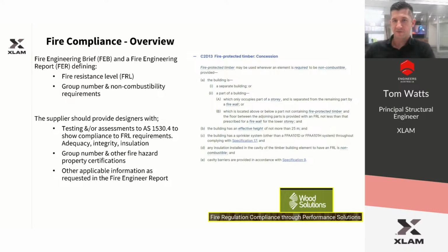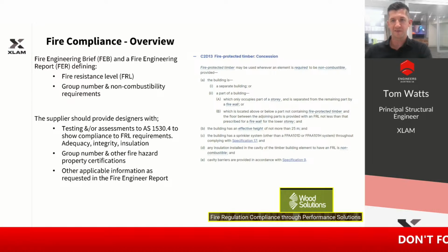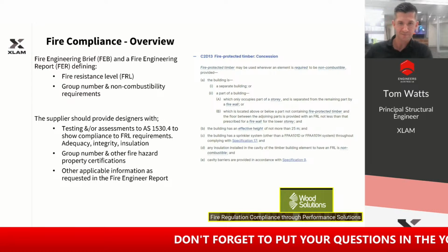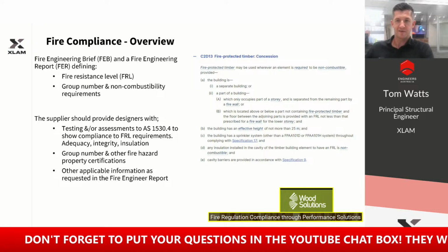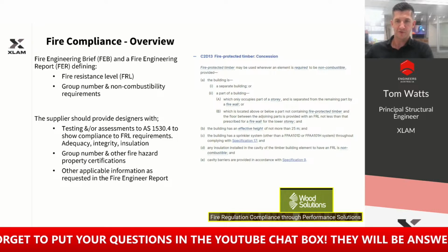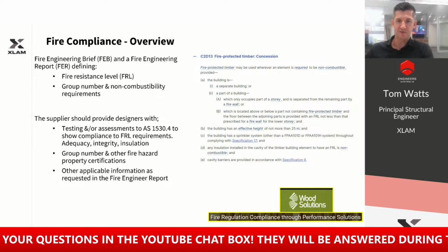In terms of the process that structural designers may need to be involved in, generally a two-stage reporting process is adopted, comprising initially the fire engineering brief, followed by the fire engineering report. This process involves the relevant stakeholders who, in addition to the design team, client and building certifier, may include the fire brigade, local council, insurers or other parties. The purpose of the fire engineering brief is to communicate to the stakeholders and approval authorities what the basis of the fire engineering strategy will be.